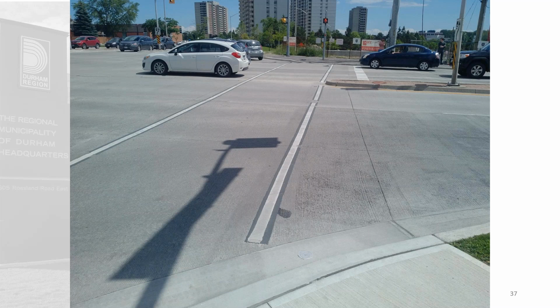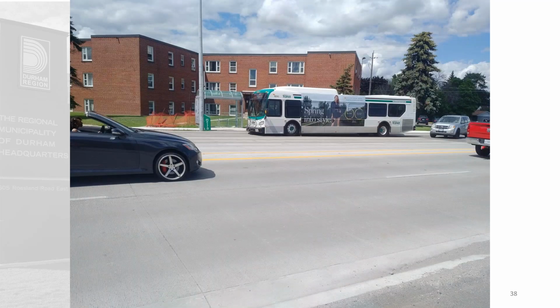And we thought about this during detailed design, but there wasn't really any way around it unless we wanted to grind out the length of the paint line and have the paint recessed into it. I know that's been done. I spoke with somebody in the west end of the GTA, I can't remember what municipality, and they did that method for concrete roundabouts. And all the paint lines, they actually ground out a few millimeters and placed the paint in that grinding. So maybe we could have done that and it would have helped this, but it seemed like a big undertaking.